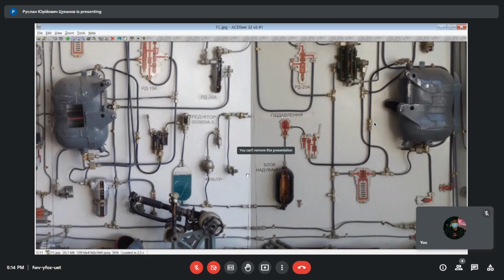The pressurization subsystem is independent, but it has 2 common devices. There is a fitting for ground connection of high pressure air to provide ground operation of the hydraulic system, actually ground tests. And in parallel, there is a connection to the air bleed port from the engine.